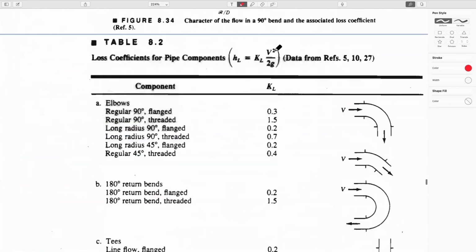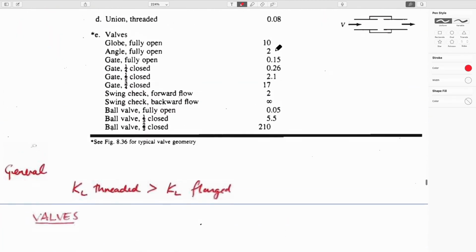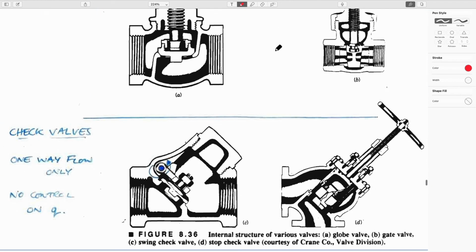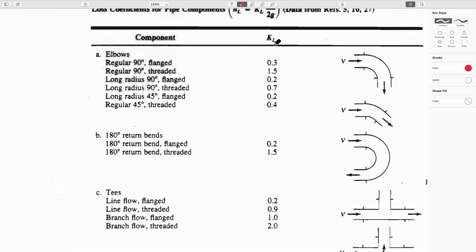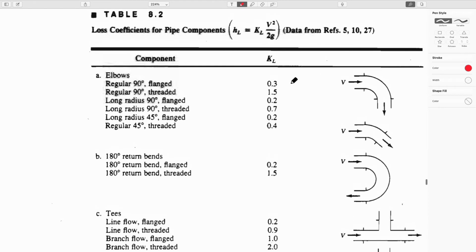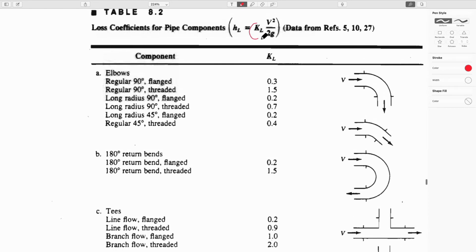And so what we'll see is that when we look at fittings, such as valves and bends, you can define a table that defines exactly this. So the head loss term that we've talked about is defined in terms of the velocity, always the velocity within the fitting, and depending on the severity of the fitting, the value of this goes up.